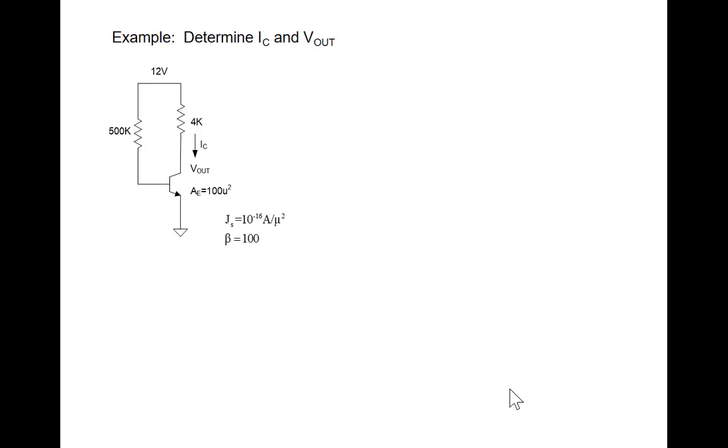Well, we have a nonlinear device, and we have a piecewise model. So what do we do when we have piecewise models for nonlinear devices? Make a guess. We make a guess for the region, analyze the circuit, and verify. At this point, unless you've already worked with bipolar devices, you may not have an intuition as to what region to guess. You'll get that intuition very quickly.